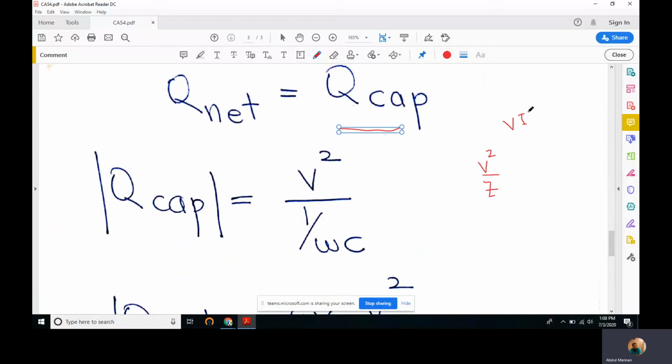So this sine term that we write here is VI sine of theta V minus theta I, which is always 1, because they are at 90 degrees and sine of 90 is 1. So for inductors and capacitors, this sine term for Q always gives us a 1, and the cos term in the case of P always gives a 1 for resistive loads.